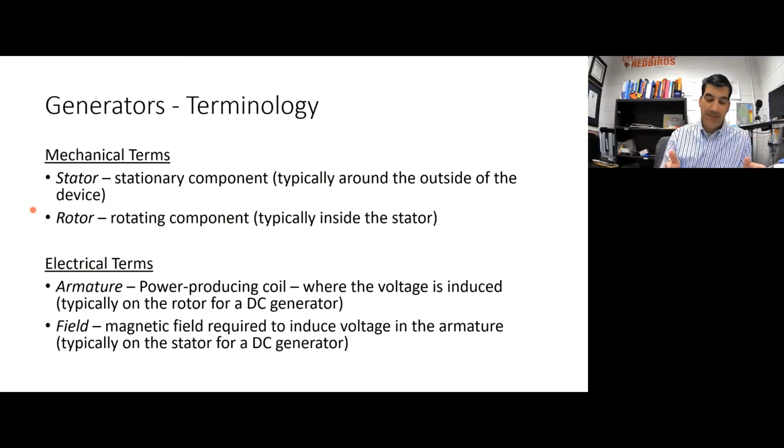And a really common one, I would say the most common one in the electrical generator industry, is the one I just described, which is to have the armature on the stator, a three-phase armature in fact, phase A, phase B, phase C, the three sets of windings on the armature, one set of windings for each phase. And then on the rotor, you have your magnetic field, and it's actually most common to use an electromagnet on the rotor for the magnetic field. And so you do actually have brushes and slip rings to send current to the electromagnet on the rotor.